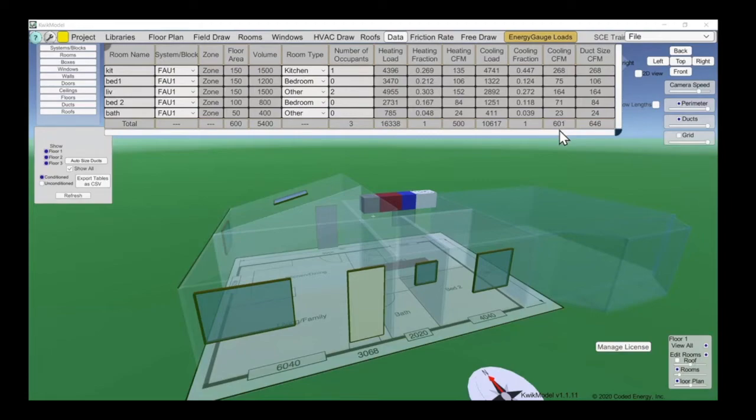And as I mentioned, it's a bit more complicated if you have a variable speed furnace. Variable speed furnaces will adjust, okay? But you have to pick a starting point. Even with the variable speed furnace, you have to pick a starting point and do a similar type of sizing criteria. But this is a simpler constant speed furnace on this little bitty house, okay? So we want to ensure we're getting the 601.